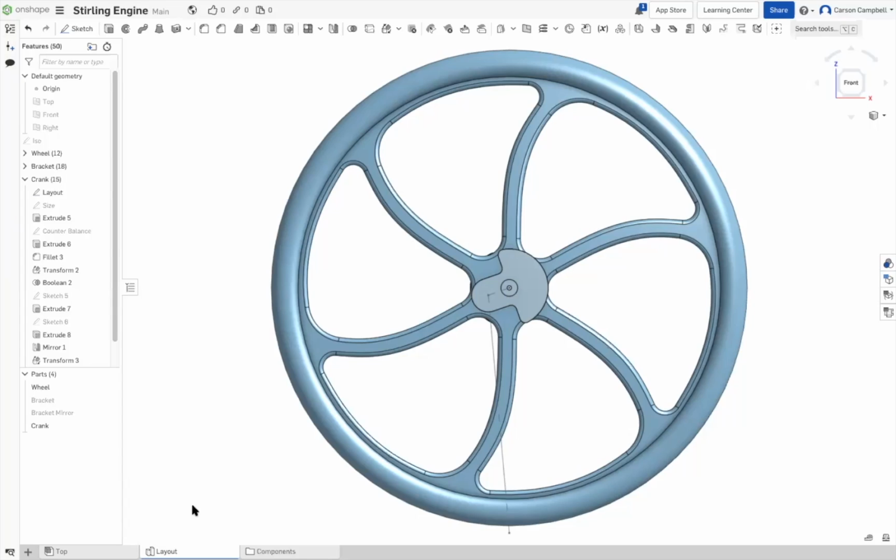The other thing I get is that I can put a counterbalance on the flywheel to counterbalance the counterbalance. And I can really tune this thing such that the center of gravity for the shaft with the counterbalances, with everything, will perfectly dynamically be centered.